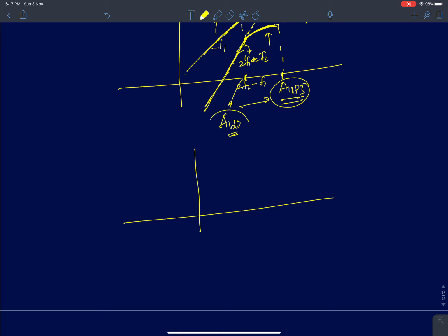Okay, I think I've said some points very fast. What I'm trying to say is that your IIP3, the third intercept point, is normally much greater than A1 dB. So what is A1 dB? It is the amplitude at which your gain reduces by approximately 11%. It's the gain compression point. So even before you reach IIP3, the gain starts reducing significantly. You can't directly measure IIP3, so you have to measure it using some other mechanism. One is extrapolation. Now we are seeing if there is any simpler way of doing it.